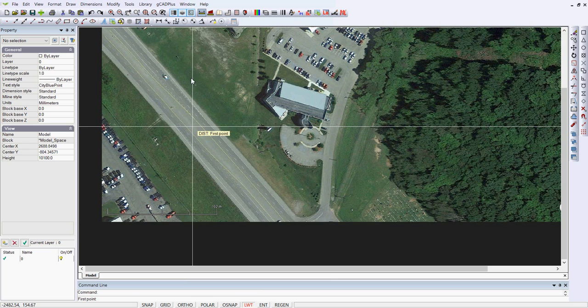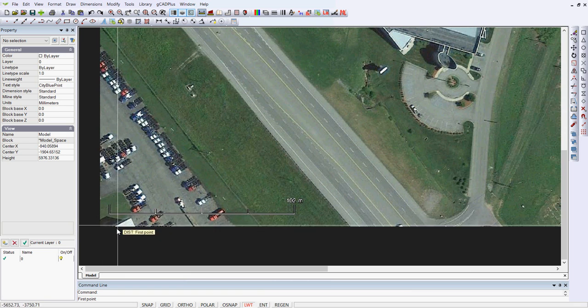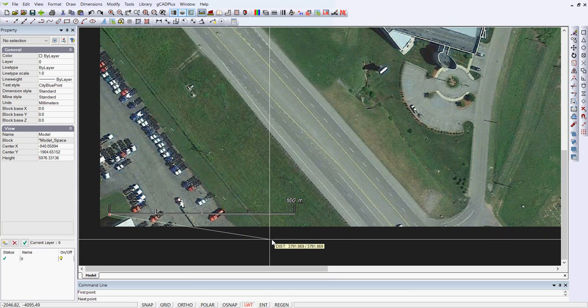But the important thing is we have a scale bar. If we measure using our measure tool, which is up here, from one side of that scale bar to another, we should have 102 meters, and we've got 4316 units. So we have to convert this and make it a full-size drawing. I'll go about doing that. That's just a matter of doing the calculation and then scaling the image.